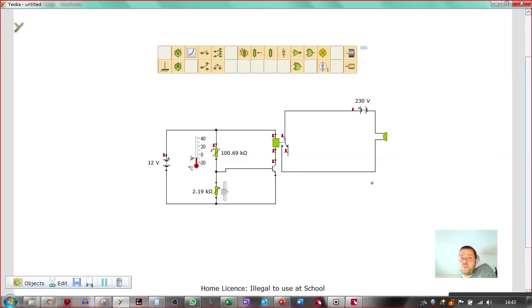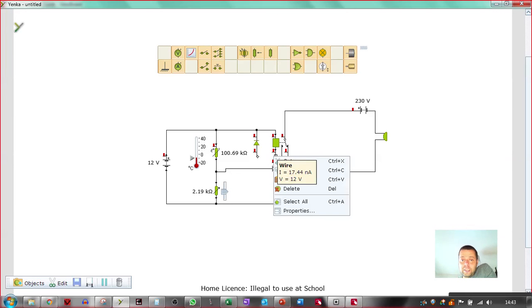Ooh, so what I've got now is a low voltage input side at 12 volts and a really high energy output side. This might not work, it might fail. Obviously it will fail because I don't have a diode in, but a relay is an electromagnetic device, so I have to protect the transistor from back EMF in the relay coil.